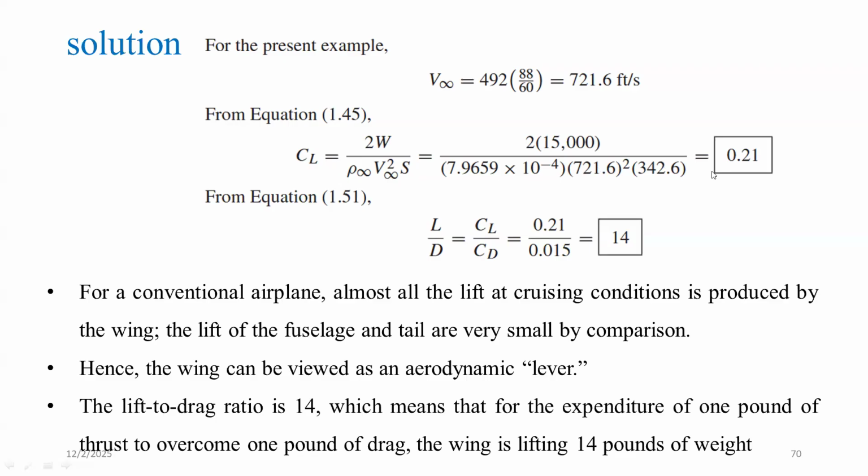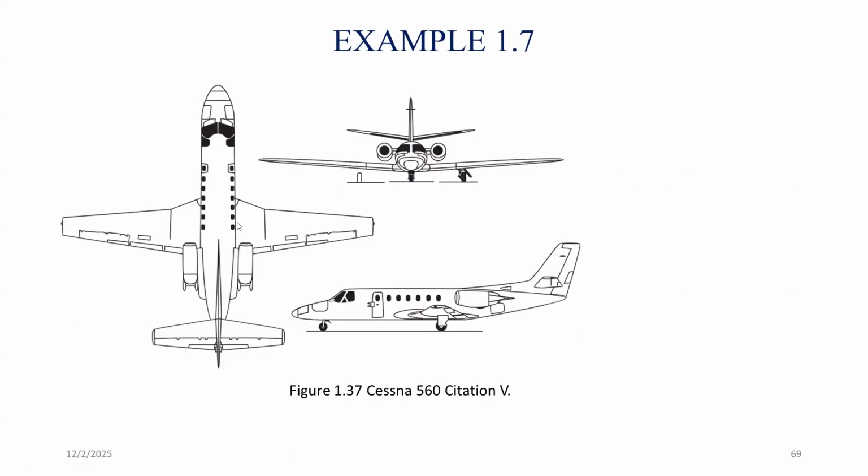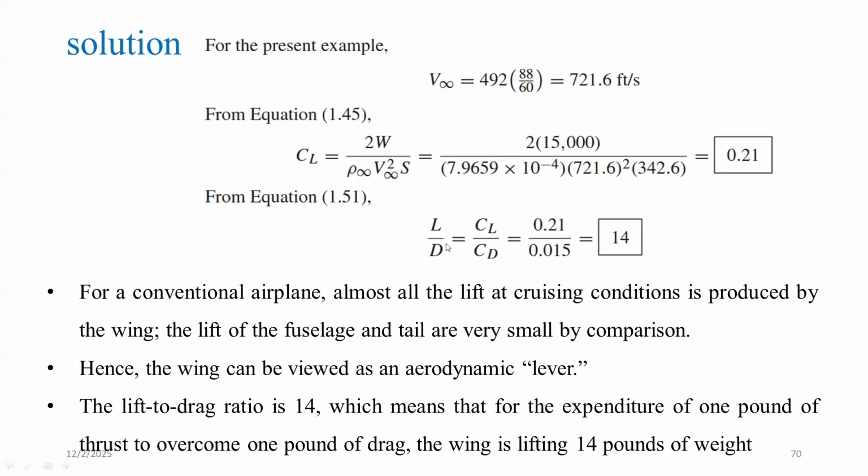Just substituting the values, we get 0.21 as the lift coefficient. Then the lift to drag ratio: the drag coefficient 0.015 is given, so L over D.